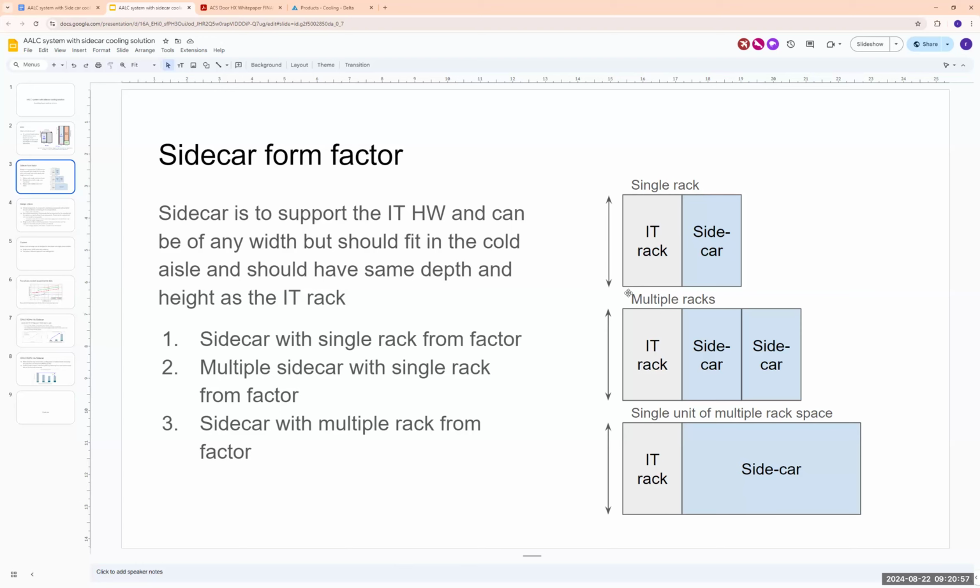Yeah. CDU is nothing but a cooling distribution unit, right? Most of the time, CDU is termed as a liquid-to-liquid CDU, and when you have air assisted that is independent of the facility water, that could be termed as a sidecar or a large heat exchanger, and you are attaching this to a single rack.